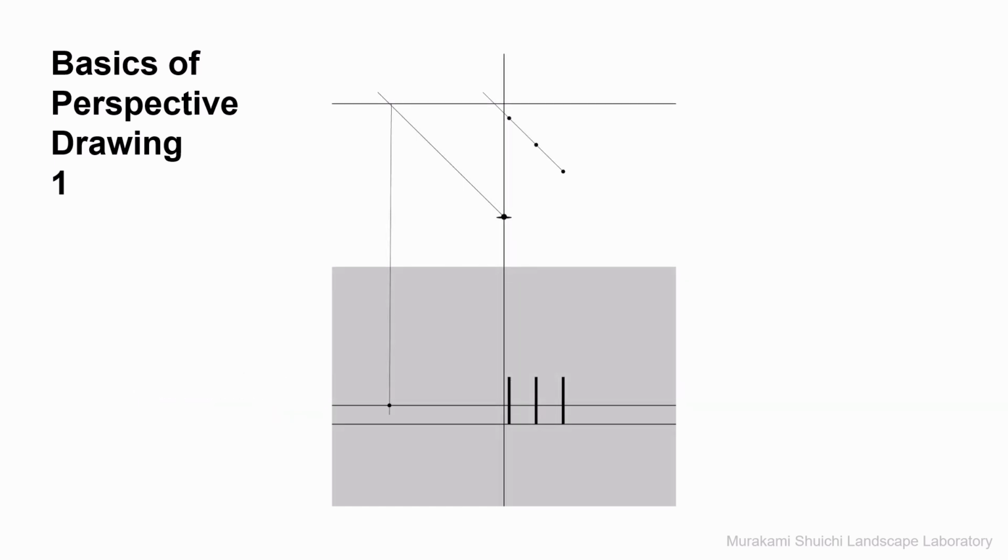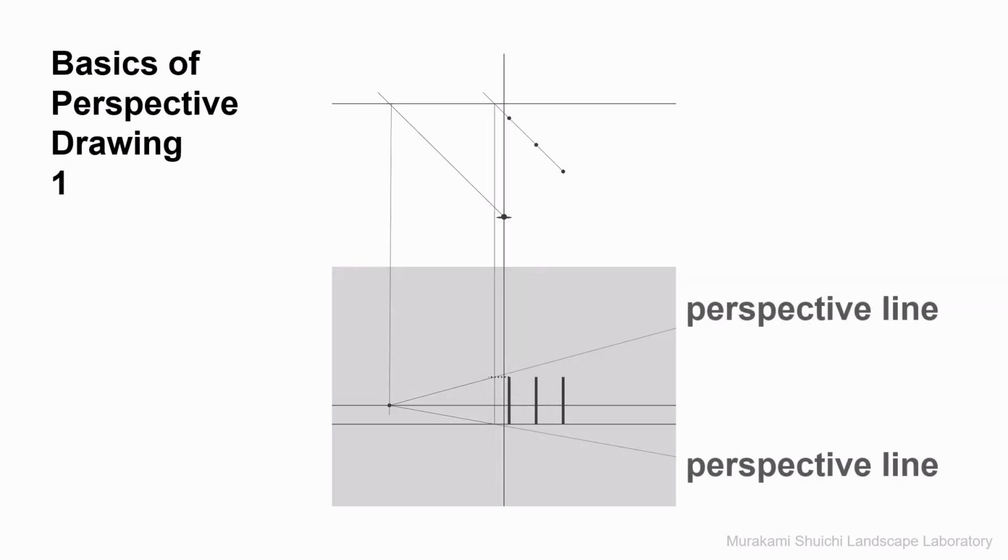Extending the column line to the projection line. Then from the intersection, drop the vertical down to the ground line of the perspective plane and mark the column height as in the elevation. Connect the vanishing point to the top and bottom ends of the column height in the elevation, and extend these connections so that they become the perspective lines of the columns.